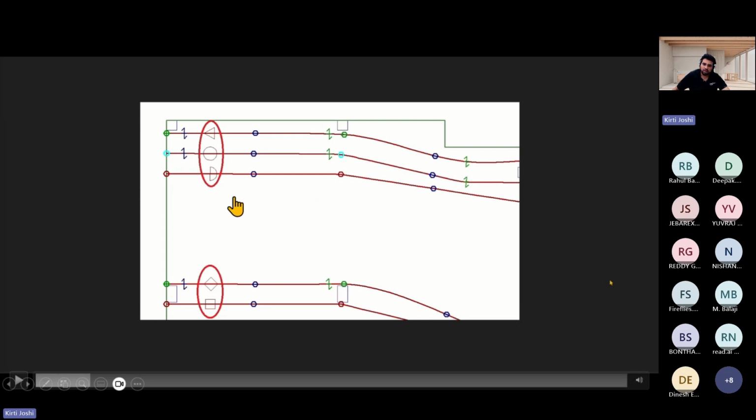It is applicable for a tendon with 1 to 6 strands, as you might be familiar. One strand is designated by the semicircle, two by the circle, three by the triangle, the diamond represents 5, and 6 strands are represented by the hexagon, which you can typically see on the shop drawings.